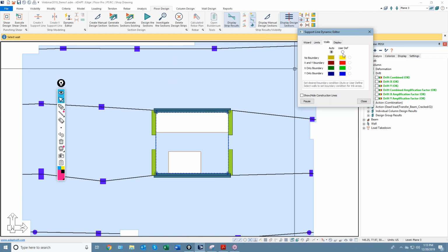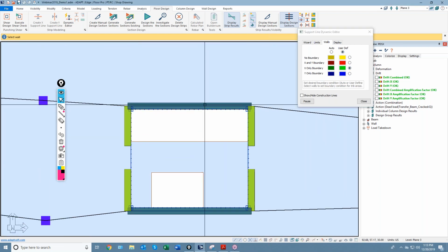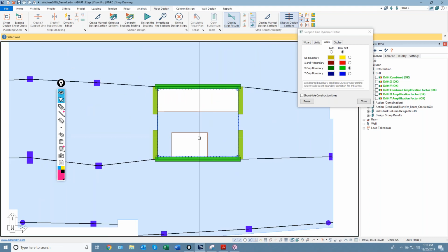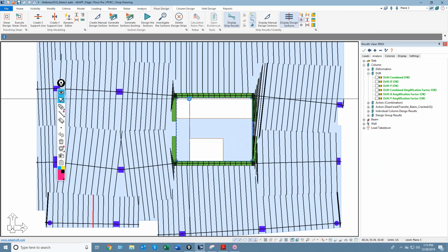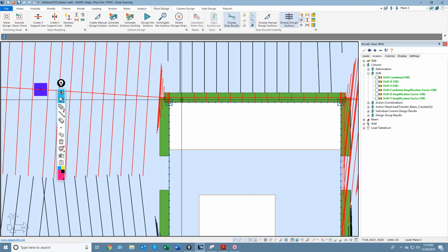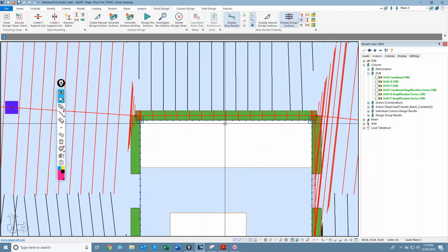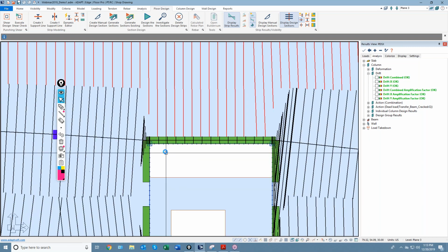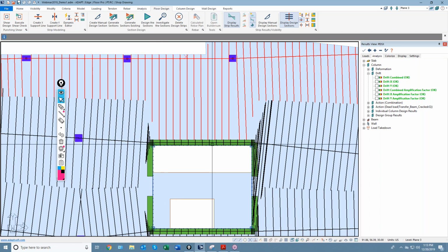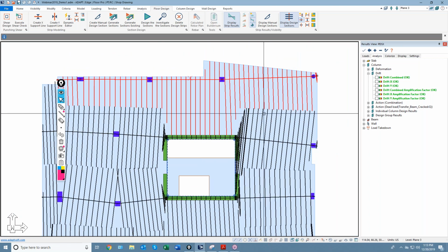So I'll go ahead and select user defined. I'll define these as an X only boundary. So I'll just click on the wall and specify the boundary. I'll close that. When I regenerate the strip, notice that the program creates a very small section over the wall automatically. You would have had to do this with splitters in the previous versions of the software. And notice it sticks out some tiny distance, and then the sections above actually extend all the way down to the wall. So this is one way of handling this, but I might say, well, this integration line is too long. I don't want to integrate a section that long.